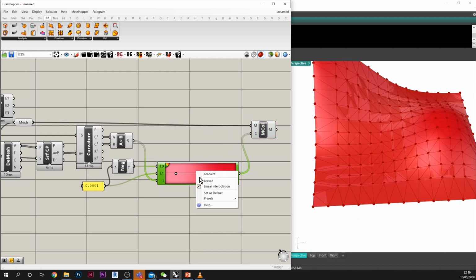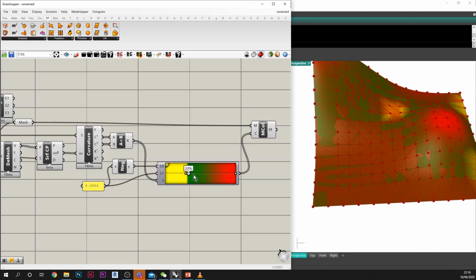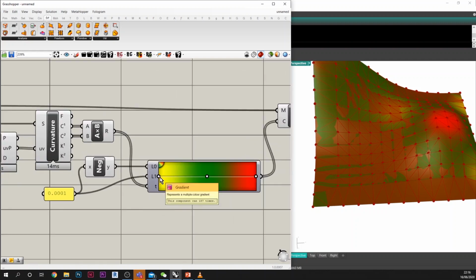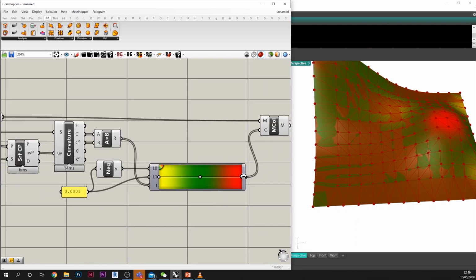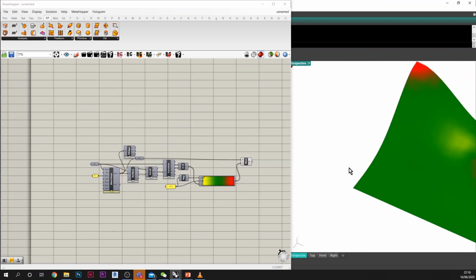And we just need a good preset color. Okay, I'll let you put the values you like, but let's put the green as developable surfaces. This will be negative curvature, so anticlastic, and synclastic for positive curvatures. To see it better, let's display off here.